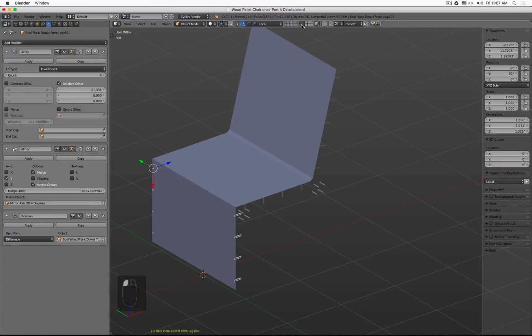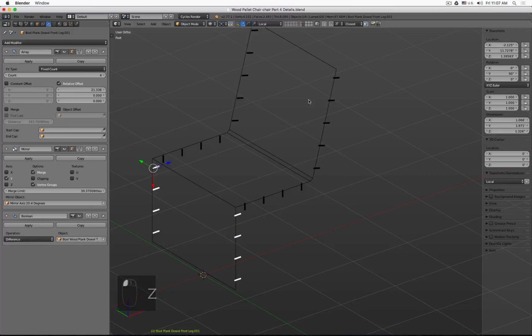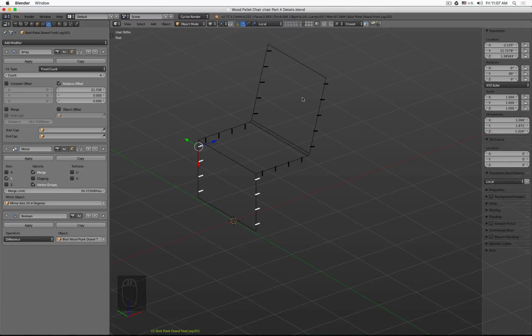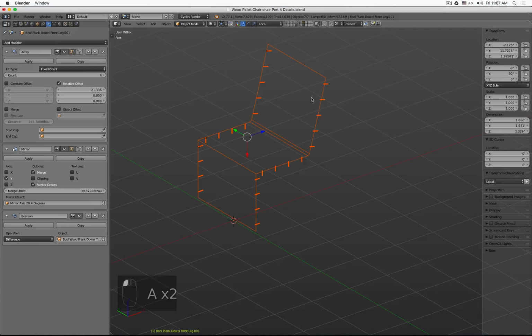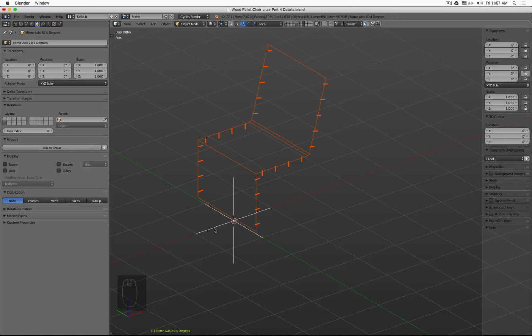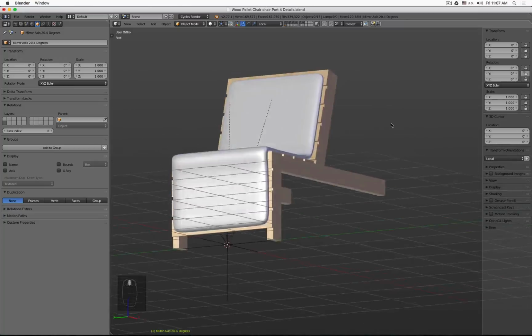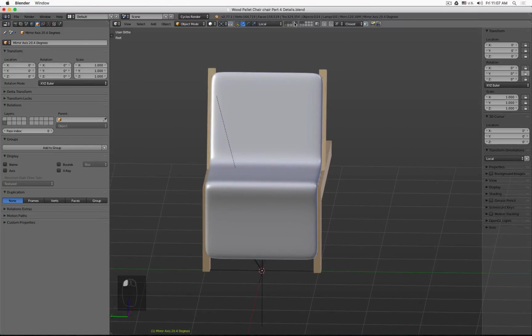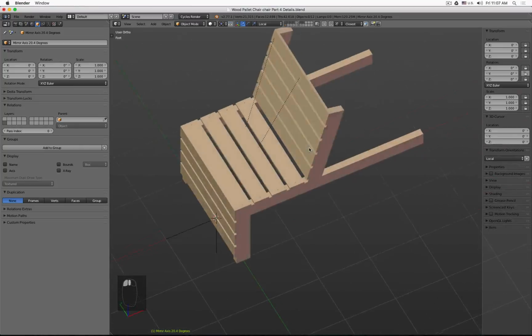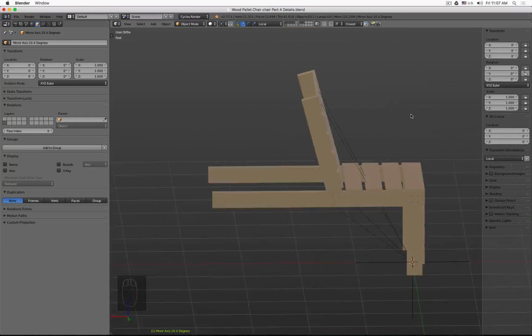But also here, make sure that everything we select here will be parented. So all this, so the wooden dowels and the Boolean wooden dowels, and then the surface that trims them. Select the empty, Control P, parent. And then this we can all hide. And I would say we're done. So now we have created a nice extra detail for all these wooden parts.